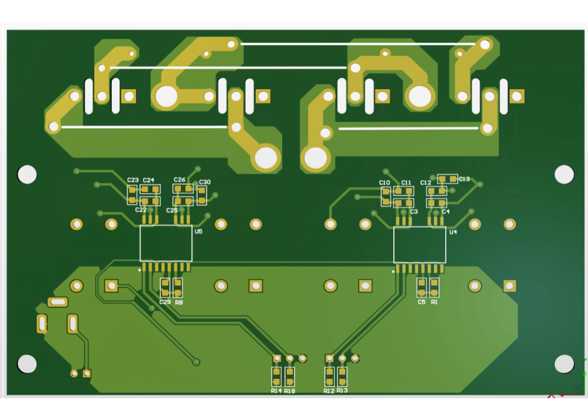The high-current, high-voltage regions are routed with wide copper posts and are physically separated from the control side by clear spacing, isolation gaps, and dedicated routing channels. You can also observe that no signal tracks cross the isolation boundary, and the routing ensures that creepage and clearance distances are maintained throughout the layout.